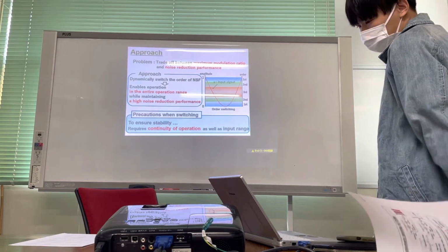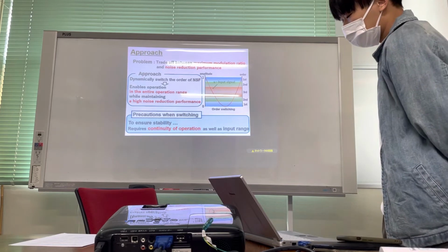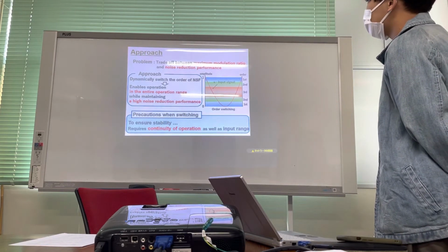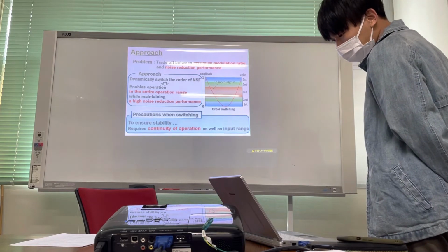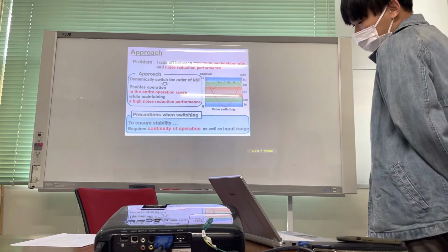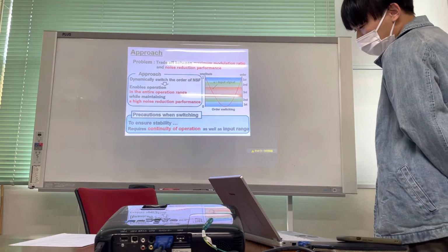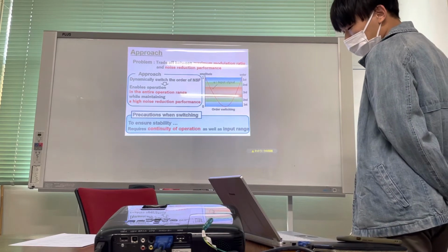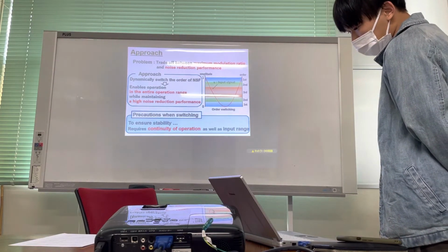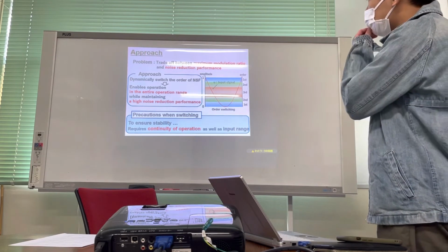Next, I will explain the approach in order to achieve both the wide operating range and high noise reduction performance. We tried the approach of a variable order delta sigma modulator. The proposed modulator dynamically switches the order of the noise shaping filter.